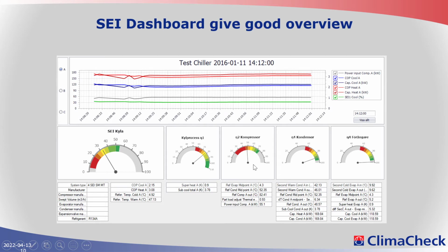the compressor efficiency. Here I immediately see that this compressor is running at very low efficiency. So this is then of course the reason to my lower efficiency, is that my compressor is either worn down or it can be part load, but it's running terrible. So it's not going to be what I desired of the system. So that's clear.